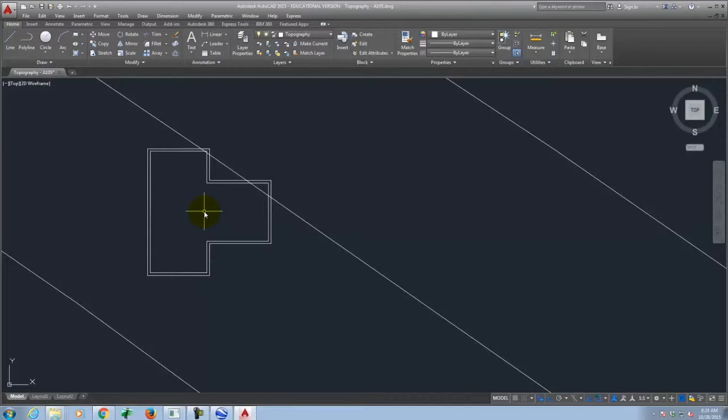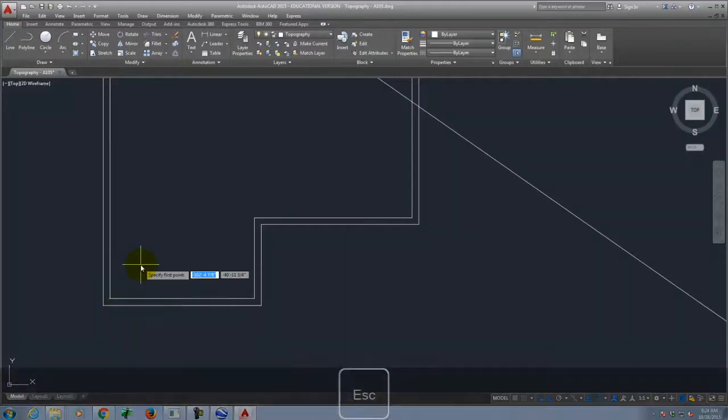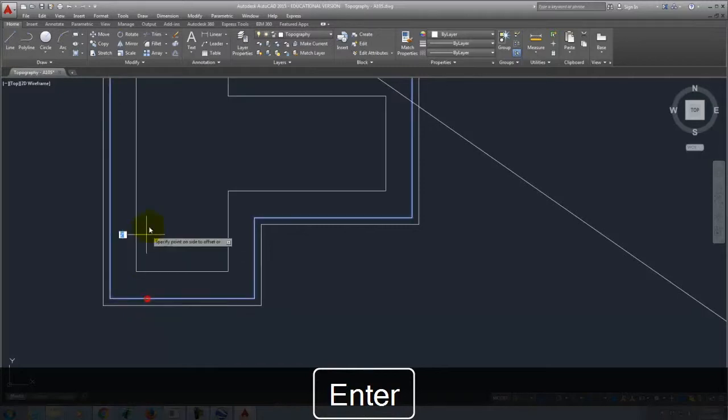So I have here flooring. I have some tile flooring in the kitchen. I have drawn in kitchen cabinets, a sink, a stove, right, that kind of information, as well as the windows, right? So if I were going to draw in, for example, the kitchen in this area here, right, I'd start with the kitchen cabinets. The kitchen cabinets in this section would be 24 inches from the wall. So let me just go ahead and do an offset at 24 inches from the wall, something like that.